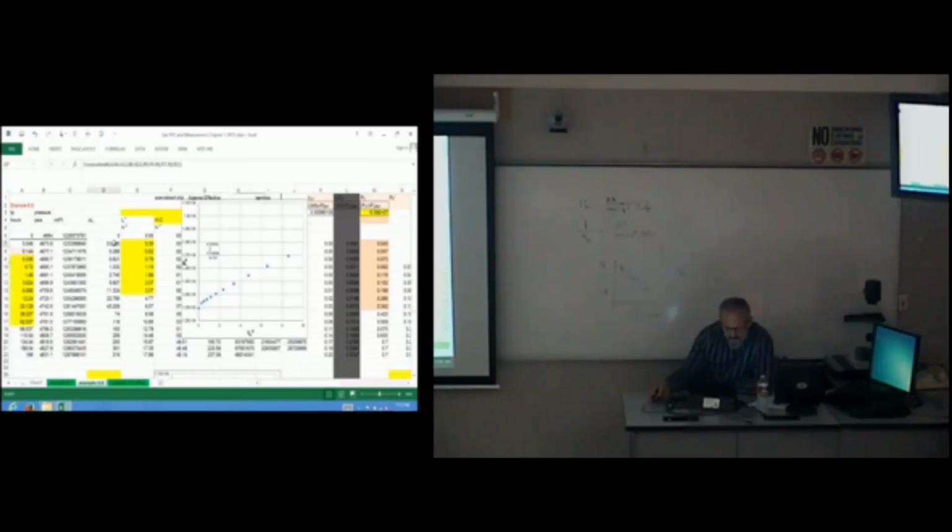Data between the 2x point is a linear flow. 4, 5, 6, and 7. That's the data that I should try to calculate a slope with to get my square root of kxf, which will result in my frac length. Okay, so I'm going to get a different answer here, but let's check.